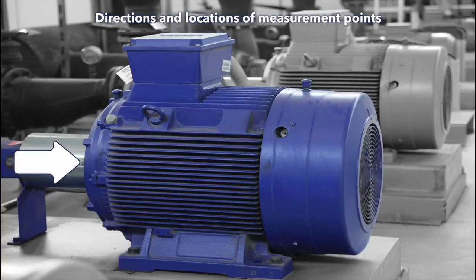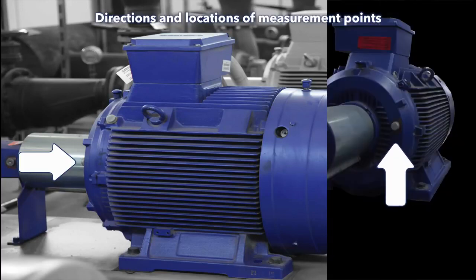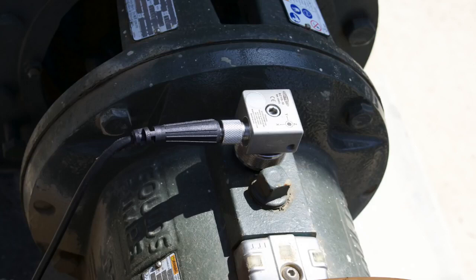You should also measure one axial point. Don't measure the axial direction on the motor non-drive end, but measure it near some joints of individual components, for example near couplings. You can use a triaxial sensor for measuring all three directions in one step, but for basic condition monitoring, measurement on one radial point is sufficient.